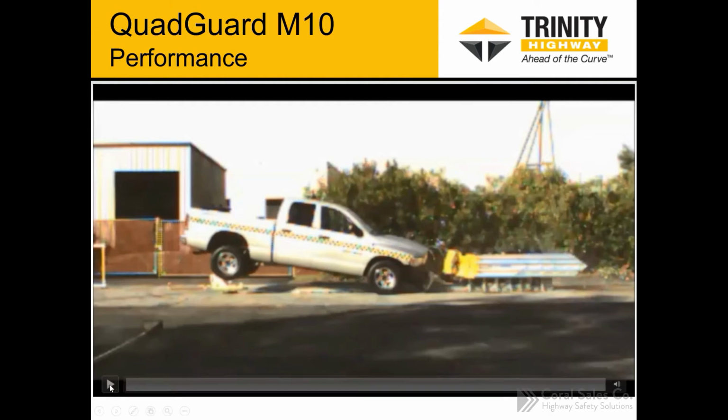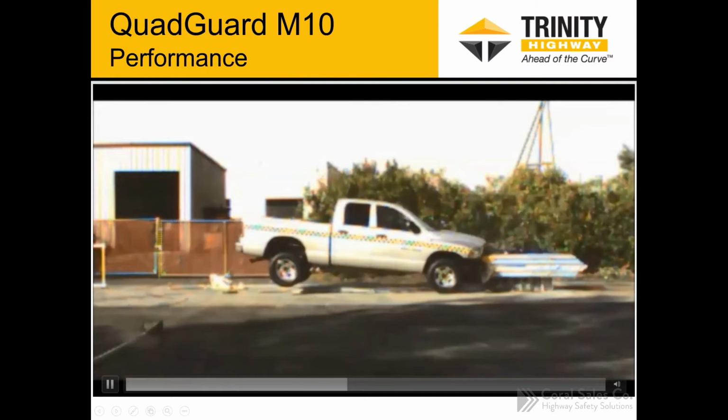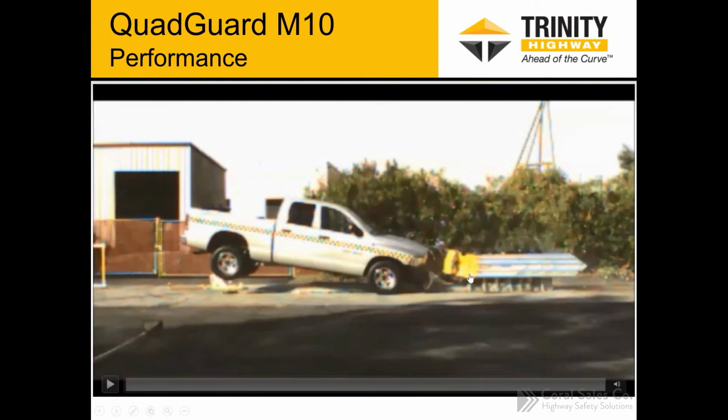I'm going to run this again. Hopefully you guys were able to see this crash test. It's pretty quick, but you can see how the system telescopes back. The cartridges are crushed. And typically, the nose is damaged to the point where it needs to be replaced as well. But the idea is to come in here, pull these systems back out, replace the cartridges, put a new nose assembly on it, and replace that cartridge as well. And then it's ready to be back in service.